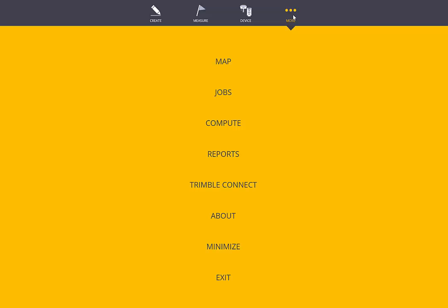So with the addition of importing a PDF file, that gives you the flexibility to simply take the PDF that the general contractor or the engineer, whoever has given you, and you can load that PDF right into Trimble Field Link. Now there are some caveats to the PDF. It only takes a vector PDF and not a raster PDF.